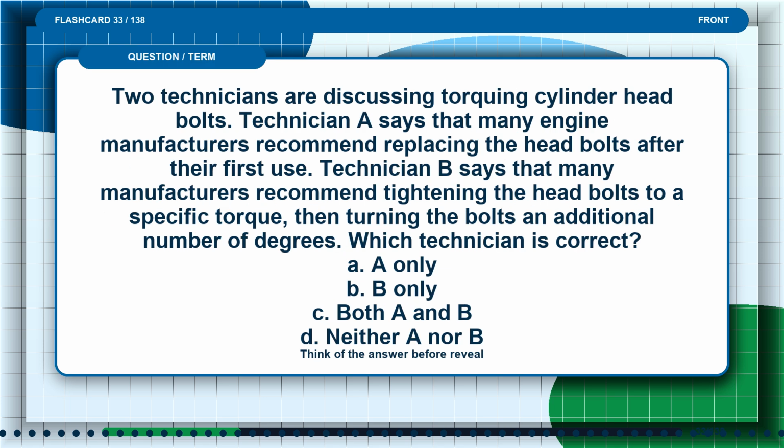Flashcard 33. Two technicians are discussing torquing cylinder head bolts. Technician A says that many engine manufacturers recommend replacing the head bolts after their first use. Technician B says that many manufacturers recommend tightening the head bolts to a specific torque, then turning the bolts an additional number of degrees. Which technician is correct? A, A only. B, B only. C, both A and B. D, neither A nor B. Pause and think of the answer before the reveal.